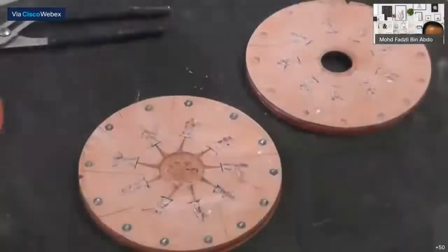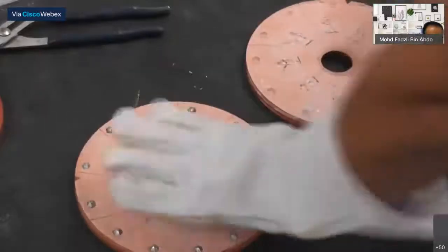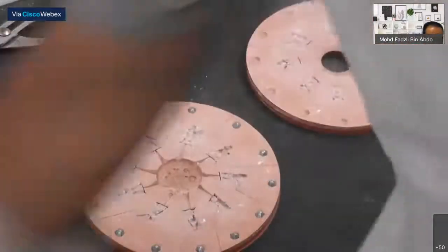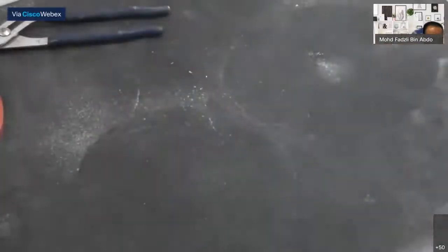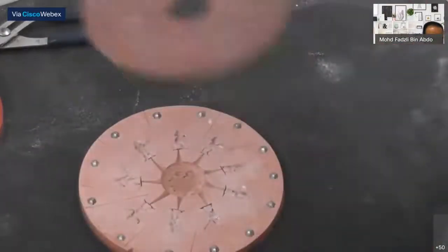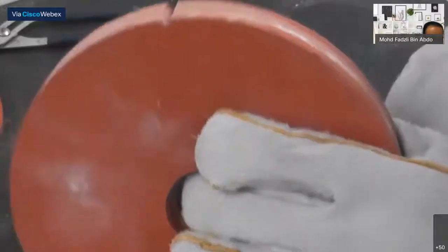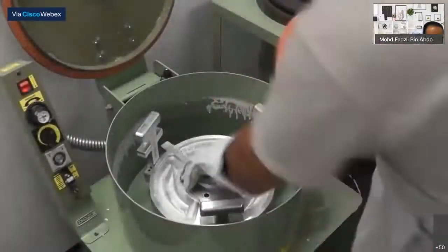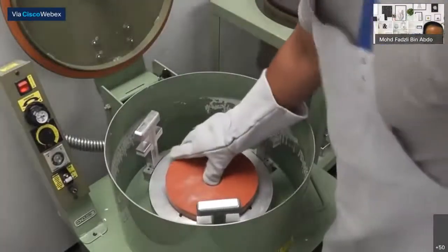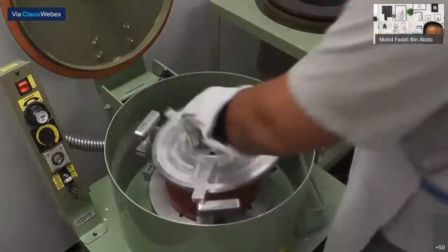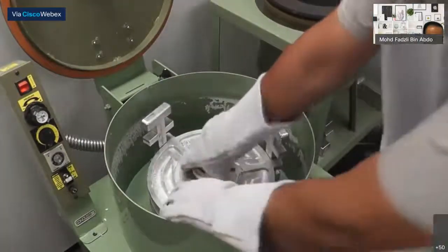Okay, so basically the process starts with our 2 mould halves. We just need to dust it with this fine talcum powder kind of material. Line up our 2 mould halves, which we can see that little V, and when we line it up it'll lock into place. Then this needs to go on the spin caster. So then this goes into the bottom of the caster. Make sure everything's still lined up. There's little locking nugs in the bottom here to make sure it's in the middle. Locking plate goes on and it just twists it into shape.